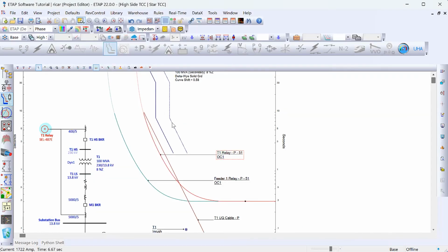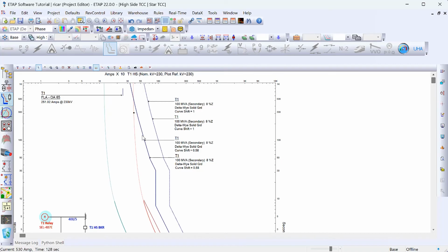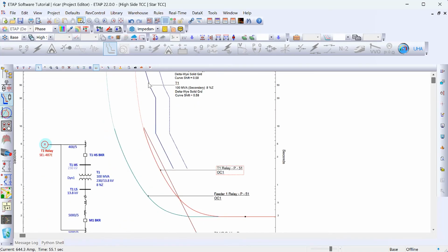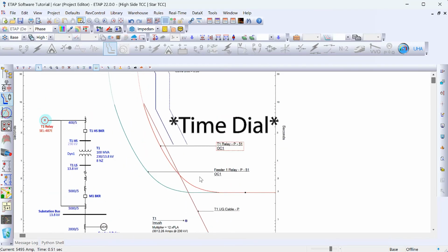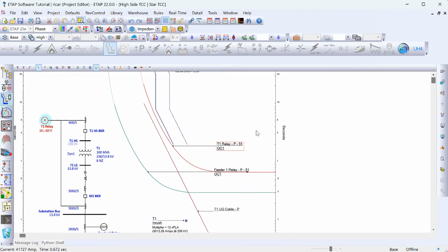So now obviously that moved the curve for the relay all the way here to the right. And we have these damage curves over here for the transformer. I want to select my pickup such that I'm just below that damage curve. So again, this curve over here is the damage curve for the transformer. We selected the pickup of our overcurrent element for the transformer, but I'm going to move this curve up such that it just barely touches that curve. So essentially, I'm going to leave enough room downstream for coordination by moving this curve as close as I can to the damage curve of the transformer.